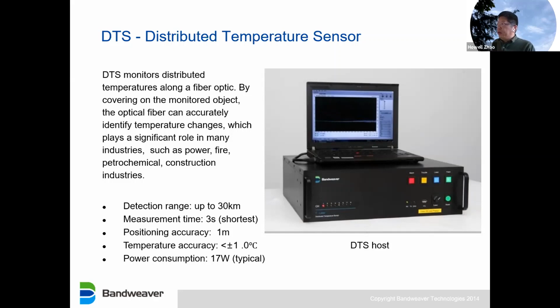After the photon detectors, there is more analog electronics, then digital electronics and the software. So in this black box, we have optics, hardware, and software. It's a standalone working system that can monitor the temperature along the fiber optical cable, give an alarm, and give the trigger to the relay, connecting to the industrial system.